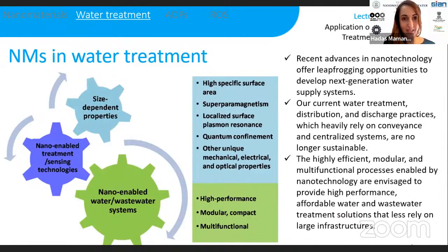If we want to design something that would be practical for environmental use, we need to have the technology working at pH between 7 to 8. We need to have normal temperatures. We need, for example, to have raw materials that are not very expensive. And in addition to that, we need to actually find a way to work with the nanoparticles not in the nanoparticulate way. So for example, from the MOF, we designed granules, and these granules, we added them to a filter, okay? And the hydraulic residence time of the process should be very short.